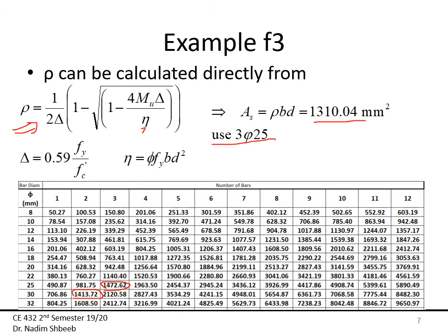25 sounds about right. If you want to use 22, then this is 1500, which is a lot larger than 1300. So I'm expecting at that point to really have more than 11-12%. You could play with it and say, hey, maybe I'm just going to use that and then maybe use a lower H. And again, it's a design. You can't play with it as much as you want. But in this case, you're lowering your concrete, but you're increasing the area of steel that you use, meaning you're using more steel for that. So this is what you usually have.